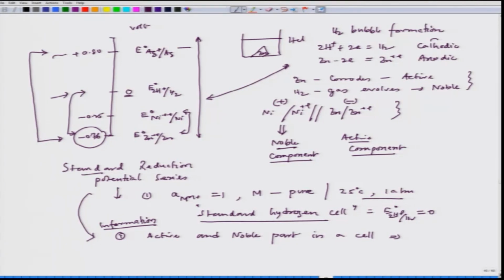For your information, if you start with a silver zinc alloy and then expose it to HCl solution, for example zinc 75 Ag25, in dilute HCl solution, after some time you will see that the particle, even if you start with a small particle, would have several small pores, and if we analyze the composition again, you would see that zinc has gone down from 75% of the initial composition.